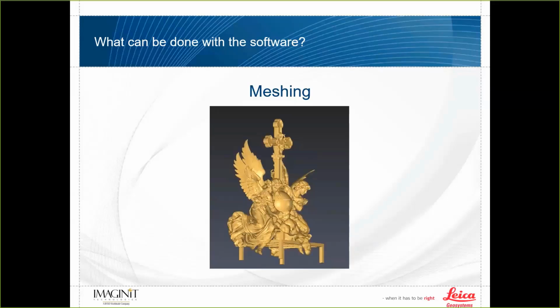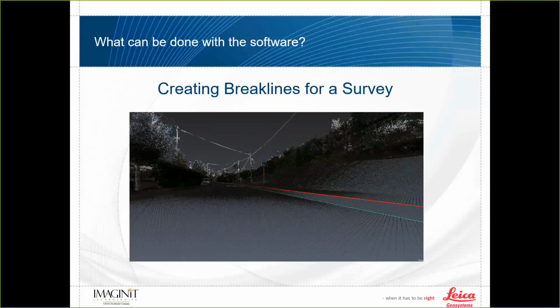And then one of the other things, I'll come back to our surveyors and our civil engineers, right? One of the things that they might want to do is be able to create break lines. Now, this is something I've done often in Civil 3D, used a point cloud and been able to kind of trace the point cloud to get a break line. Well, we'll see a little later that 3DR has the ability to do scripting and put in some parameters that will allow us to create 3D break lines almost automatically.